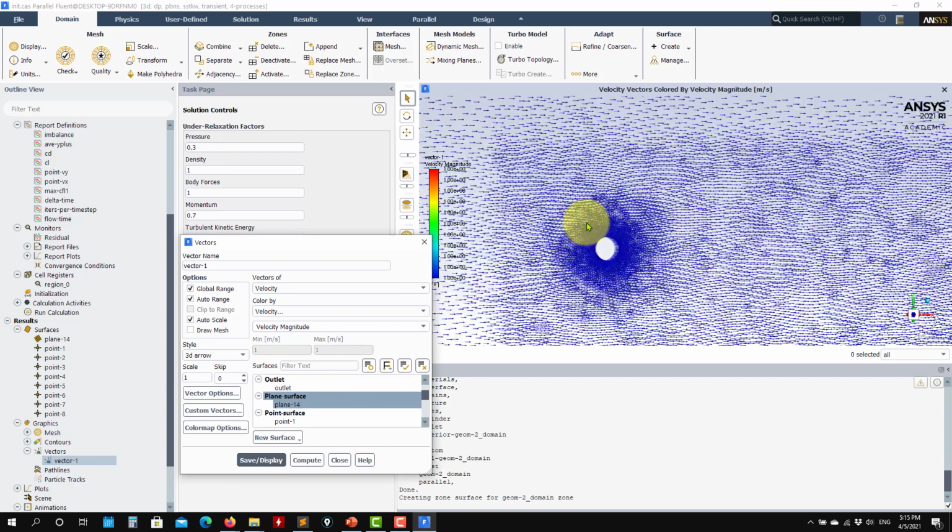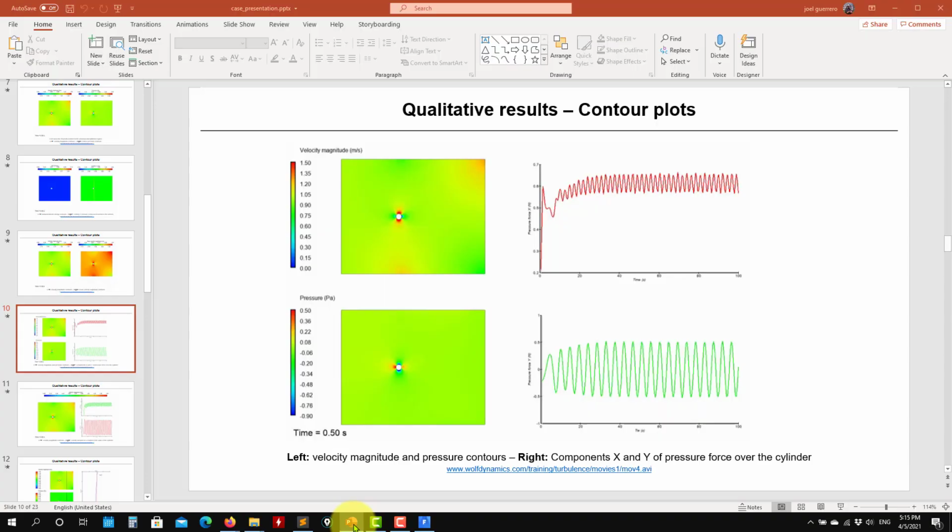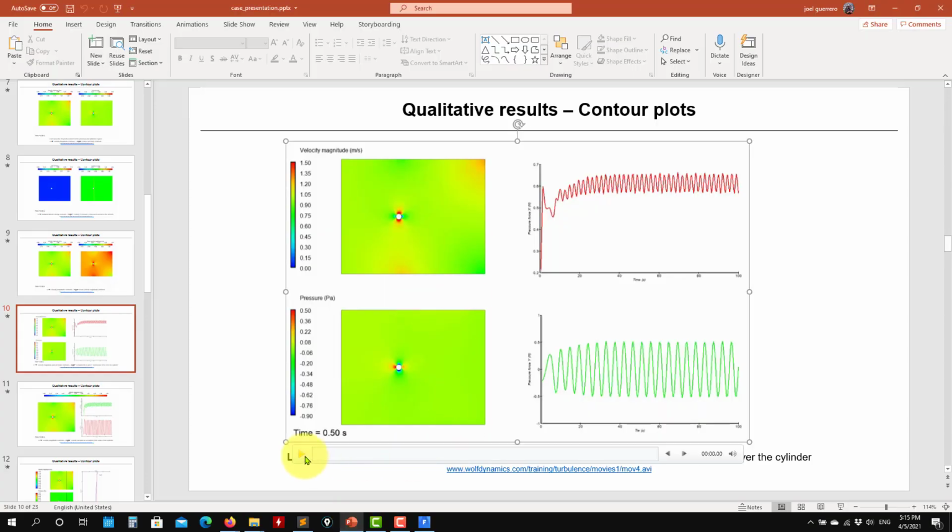Okay, so see that the flow is uniform, but remember that in this case, we have the von Karman street. And actually, in all the solutions that you have here, I perturbed the flow just to trigger the onset of this instability. Something similar happens in turbulence. You saw in the first lectures transition to turbulence. So you can perturb it, and then you can force the transition to turbulent regime, or in this case to the full unsteady.